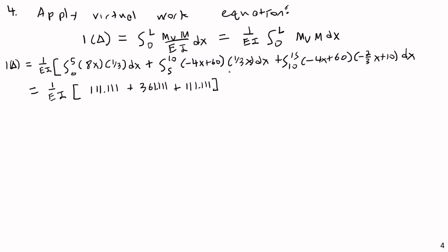And if we integrate, that would give kips per kip squared per foot, or kip squared foot squared, just from this. And then when we integrate across x, we're going to get one more unit of foot. So we're going to have units of kip squared foot to the 3rd power. The reason I'm doing this is because we're going to need to pay very close attention to our units in these things. And so here, then, we're left with 1 times delta